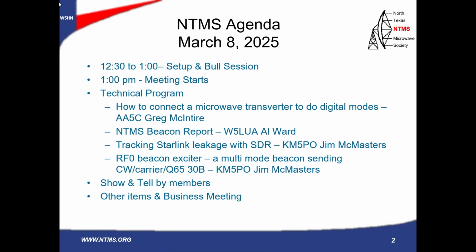Hey Jim, a comment on the RF0 using it with the 10 gigahertz NTMS beacon. Go ahead. Yeah, that multiply function in the RF0, if you were to set that to 96 and set the RF0 to be 108.0, whatever the current reference is, that should work for the beacon as a test.